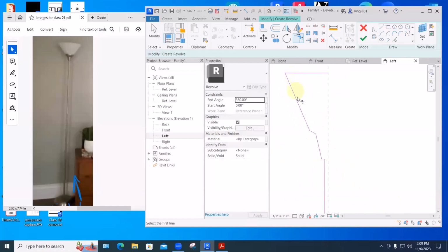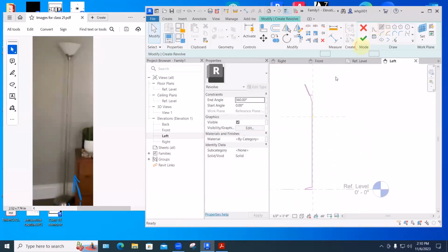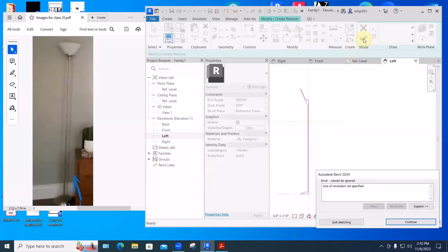And then up at the top, I need to make like this much of it, that thickness, so we'll be able to see it. I'll just call that 1/2 inch again. Then I'm going to draw this final line right down the middle to end up with a completely bounded area that doesn't have any gaps or any overlaps or any little loops or anything in it. And then once your profile is done, you hit the green arrow.